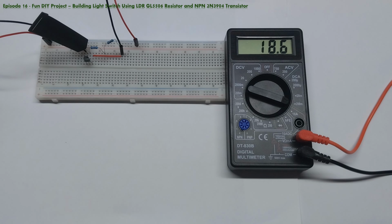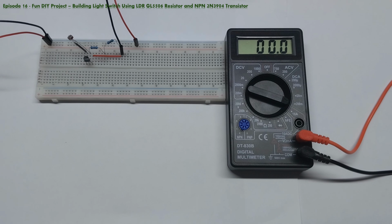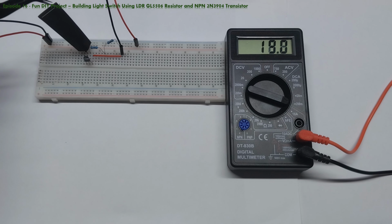If a collector current of 20 milliamperes is too small to power your load, you can always opt for a relay, or increase the power source to 5 or more volts, to build up the desired collector current. Have in mind that you will have to recalculate all the parameters of the circuit when you change the power source.